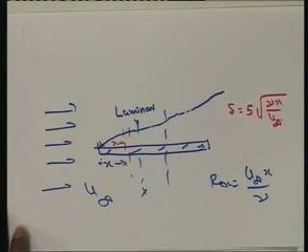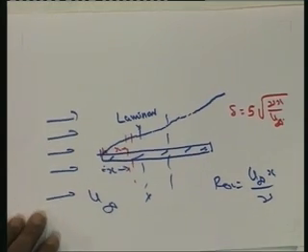The boundary layer thickness delta decreases with increasing Reynolds number. So, you can see that this boundary layer thickness, as I mentioned, when the flow velocity is very large, then the Reynolds number keeps on increasing. Then when the Reynolds number is increasing, the thickness of the boundary layer reduces, and then it is confined very near to the solid surface.